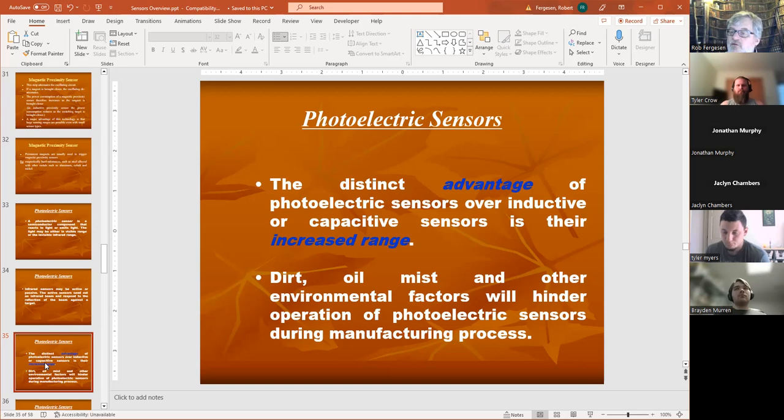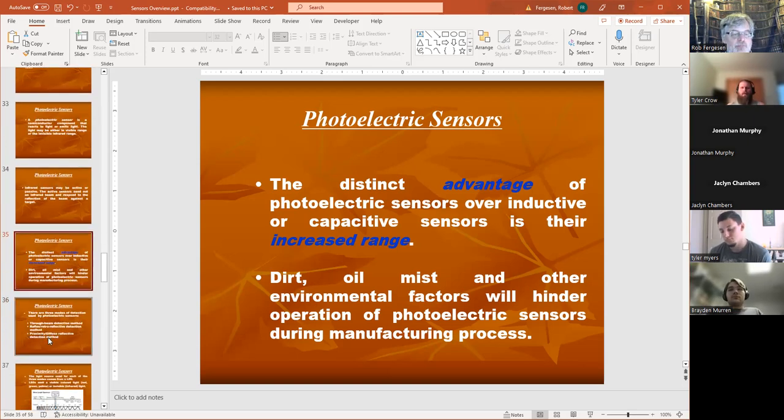However, the downside is if you have dirt or fog. They show in the movies these guys who spray hairspray to see where the photoelectric sensors are if they're breaking into buildings. I don't think that's real, but it's kind of cool. If you have anything in the air with enough mist to show that beam, it might also be reducing the intensity of the beam and will probably trigger that alarm. All those things make photoelectric sensors less reliable than a prox. But distance-wise, you can't beat them.